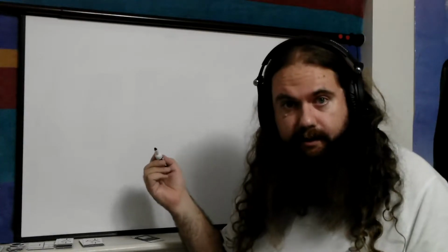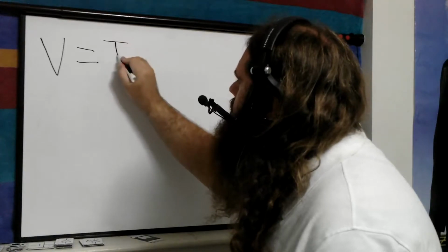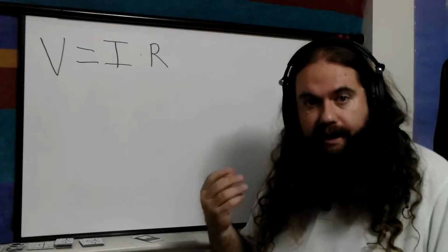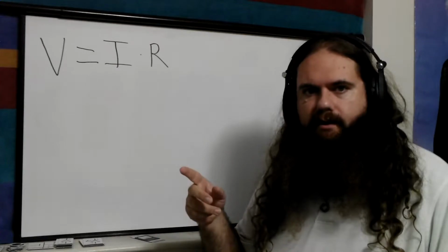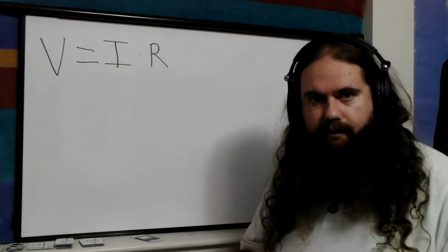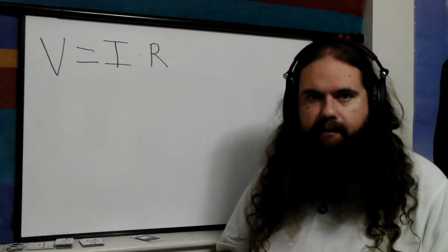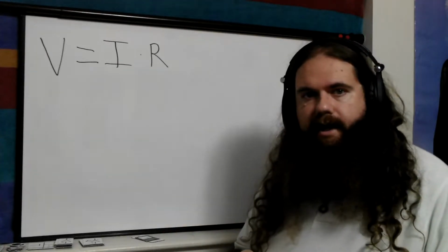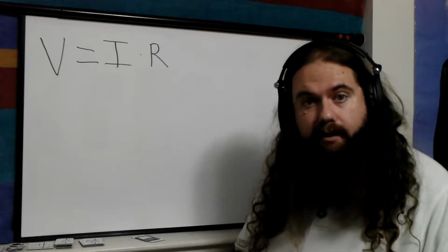Ohm's law, as used in circuit building, is voltage equals current times resistance. Now, this applies over individual components, such as a single resistor, as well as the circuit as a whole. Some devices are non-ohmic, as in they don't obey this rule directly. Diodes, like LEDs, and transistors are the primary example of this. Another example would be a fan. But even in those cases, you can calculate an effective resistance because they will have certain current draws.